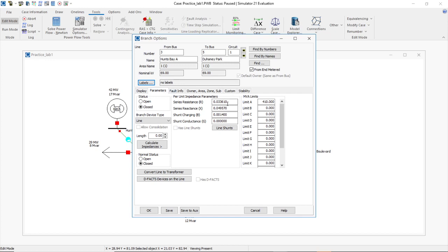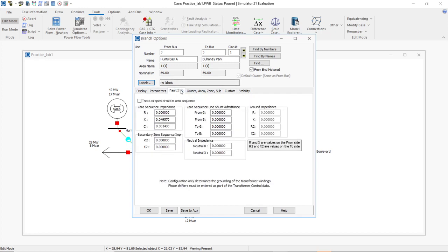After dealing with that, what I want you to do next for part C of part 1 is to double the negative sequence reactances for each transmission line and determine the impact on the bus voltages and the line currents. So for part C, they're referring that you play with right here basically. So you would double these.